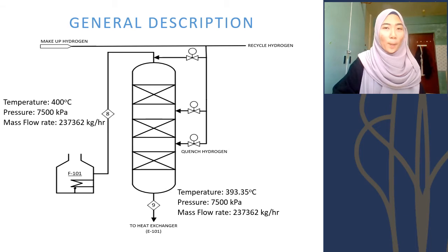The basic flow of the components in the hydrocracking and hydrotreating reactor is shown in the figure displayed. The heated mixture of these three feedstocks enters the top of the reactor, in which it will come into contact with the H2 quench at each of the intervals between the catalyst beds. The presence of catalyst will promote the reaction between the feedstocks and the H2 by passing through the catalyst beds. The treated feedstocks will be the bottom product of the reactor prior to entering the catalytic hydro-dewaxing unit.